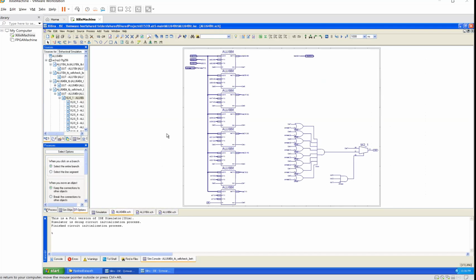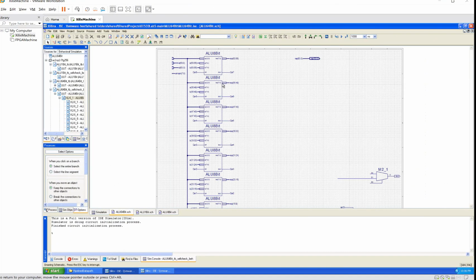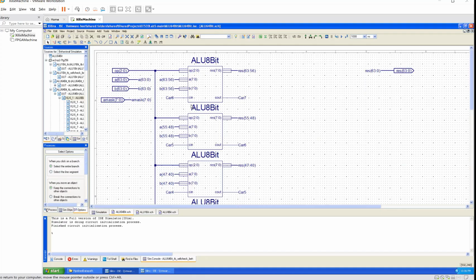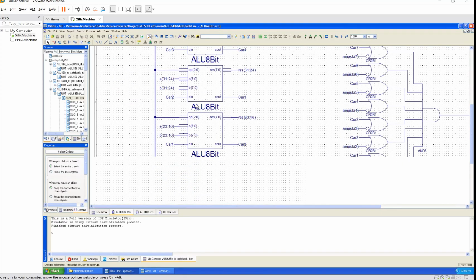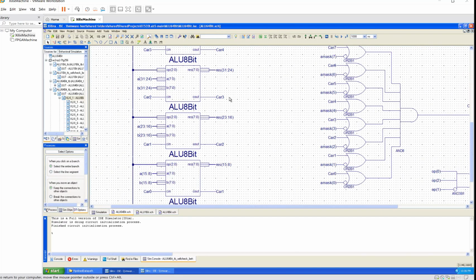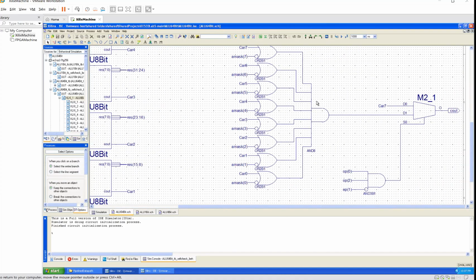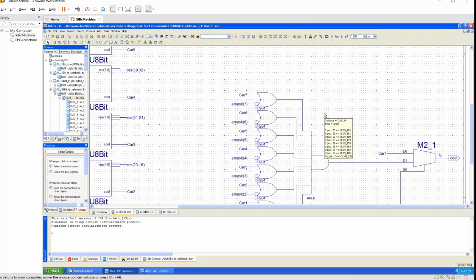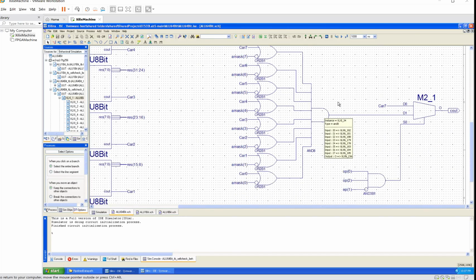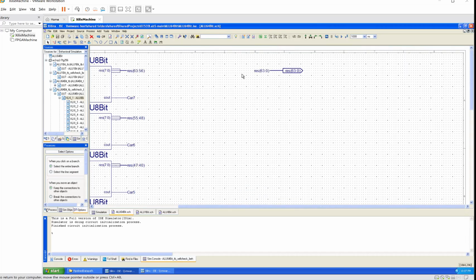For our 64-bit ALU, we have it all wired in series again. We also have a mask for our matching bits, so it works like it does in the drop FIFO in case we need that. Other than that, it is wired up completely like the matching system in the 8-bit ALU. We just incorporate that mask function, and the results are concatenated from each 8-bit ALU into a final output.